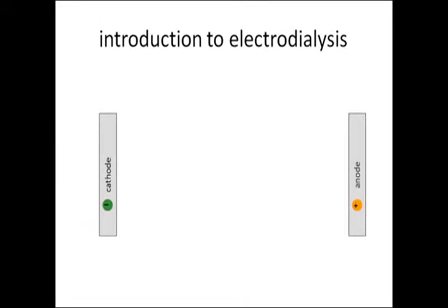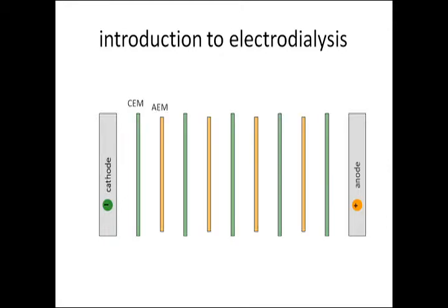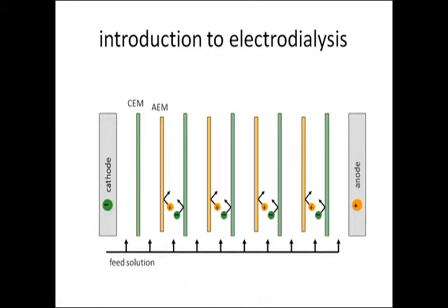The second way that we've looked at this is to use electrodialysis, and I'm not going to go through all this in detail, but basically the concept is that you provide all these membranes, anion exchange membranes and cation exchange membranes in alternating pairs, and you provide an electrical voltage from one side to the other, and ions can't move towards, like an anion can't go through a cation exchange membrane, and so it is blocked, and it's vice versa for cation.